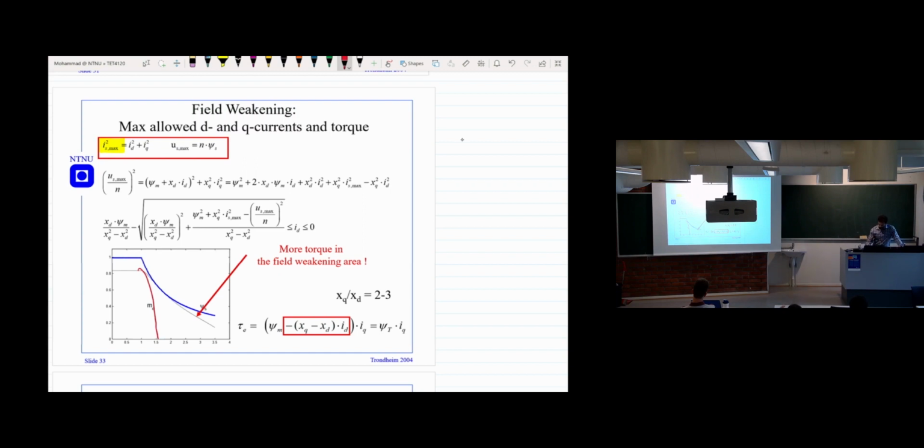So I just want to repeat, we have the torque reference, and based on the torque reference, we calculate the IDref and IQref. So that is the main purpose of our control. So once you have the IDref and IQref, then you can use the IDQ current controller. This is the current controller that we have already seen for the synchronous machine or the DC machine. We can have the current controller, a PI controller, but we need to understand this part.